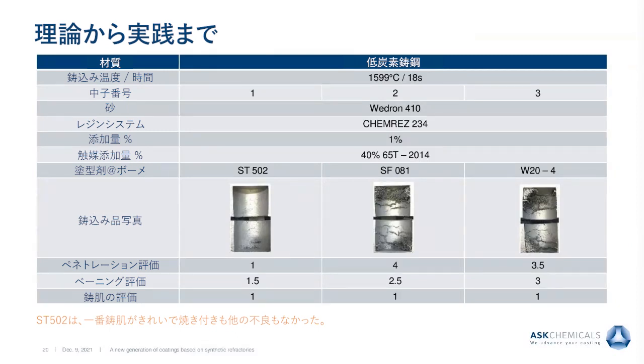As you see here, the Solitec ST502 shows really an excellent performance. There's no burn-on or other defects compared to the Zircon-based coatings, which we have compared with. You see here, very nice and clean, and here are some defects.